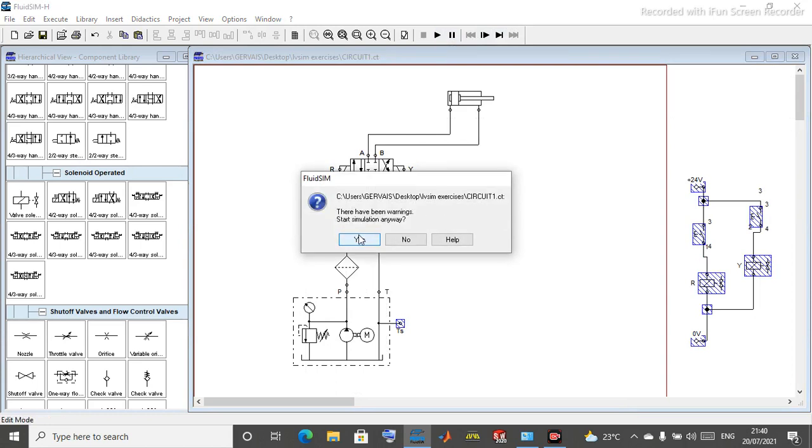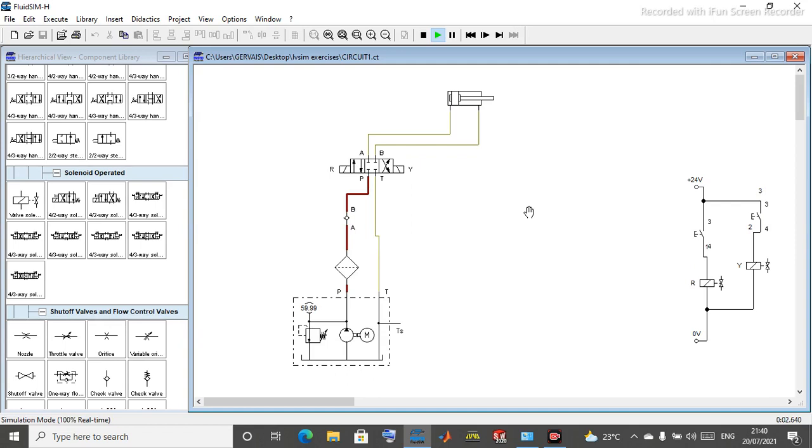Okay. You see, first we are here in off position and nothing is commanded, and this push button is there to control solenoid R. When we push on solenoid R, we are going to raise the rod. Let us see. Okay, you see that by commanding this push button, we are raising the rod, and then let us see how you can lower the rod. You go there to its solenoid on this side, which will allow the load to return back. You see now the circuit is working.